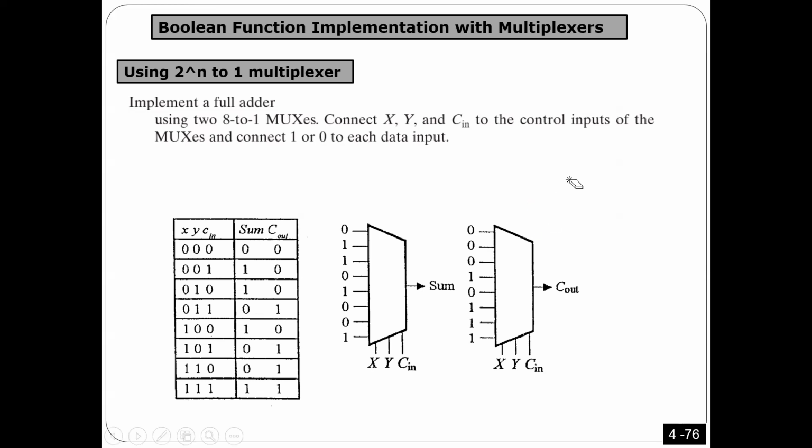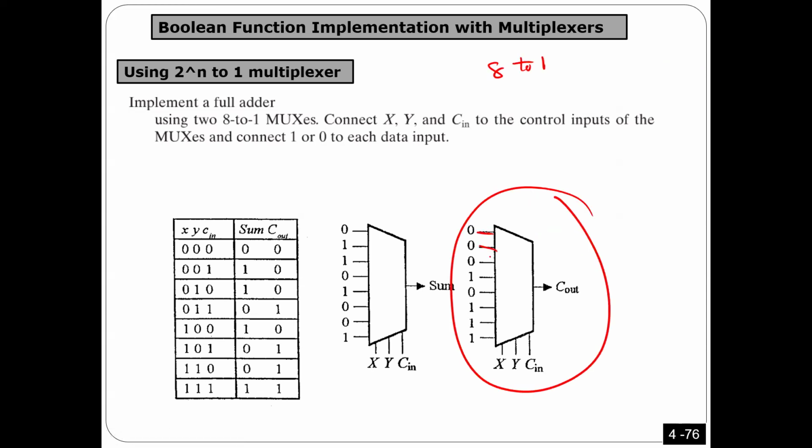If you have a multiplexer, for example, 8 to 1, we use a symbol like this one. You have here 8 inputs. You have 3 selectors, so this should be 2 to the power of 3. You always have only 1 output. And based on the selection you have here, you are going to connect the output here or here or here or here. Makes sense?